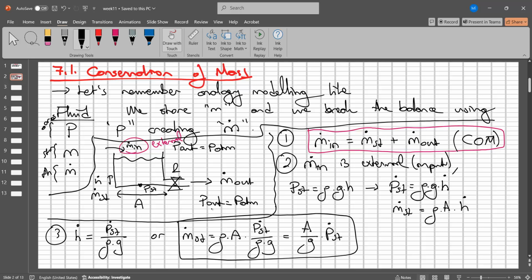Just look at the first equation. The first equation gives us the water conservation of mass. Okay? That's all. If we apply the input, we can store and we can output some parameters in here. And then m in dot is equal to what? External. And so these are the input because we cannot model it. But we can model MST dot. MST is equal to what? Rho times V, right? Volume and density. And so, if this is the case, we can write this equation, right?